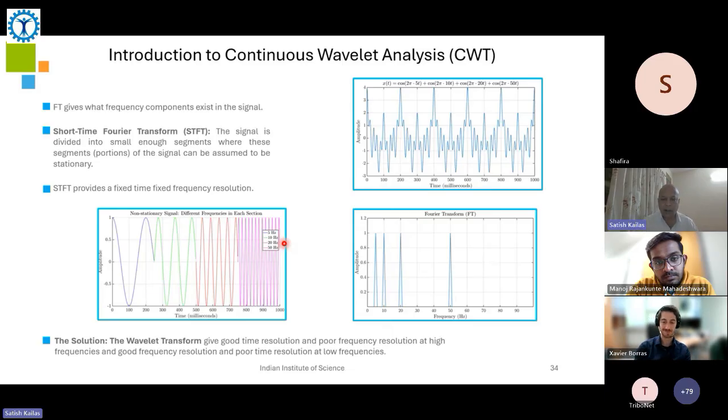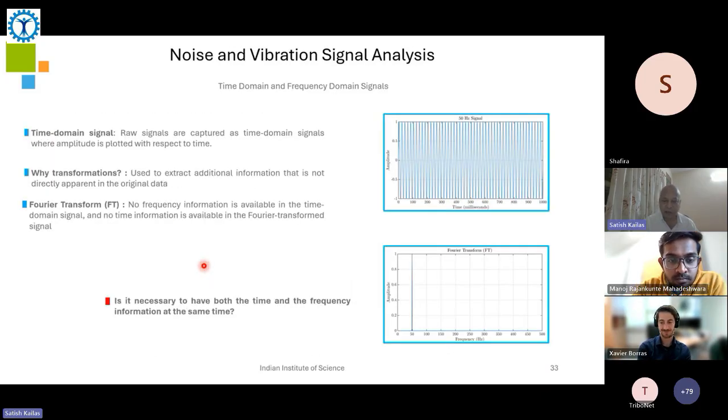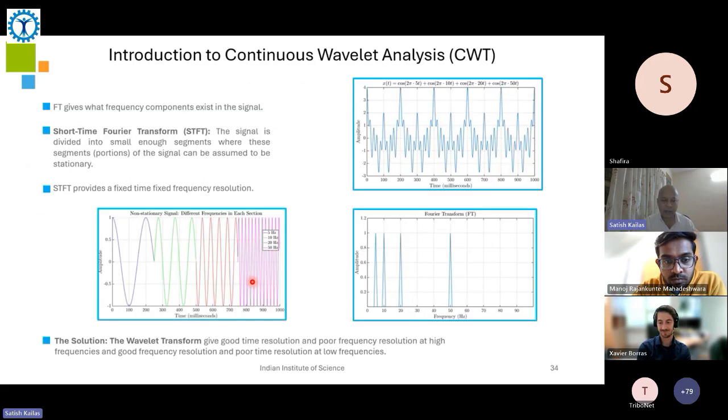But the interesting thing about wavelet analysis, which is different from the FFT, is that if I get an FFT signal, I can't rebuild the wave back. For example, if I take a wave which is non-continuous, and a wave which has all these frequencies, the FFT of both will be the same. But given this FFT, I cannot say which signal it is.